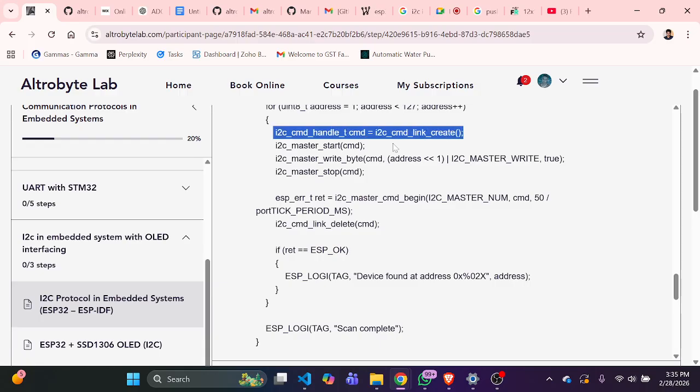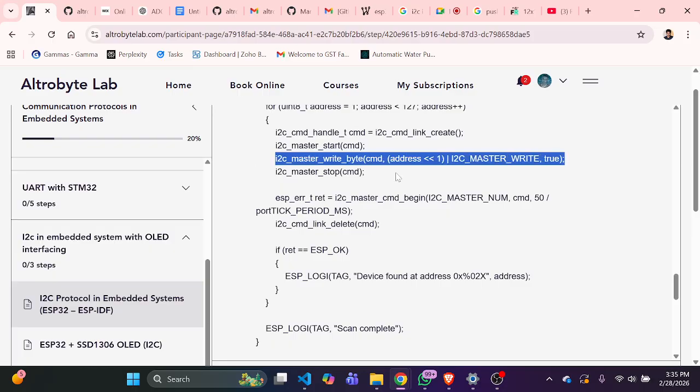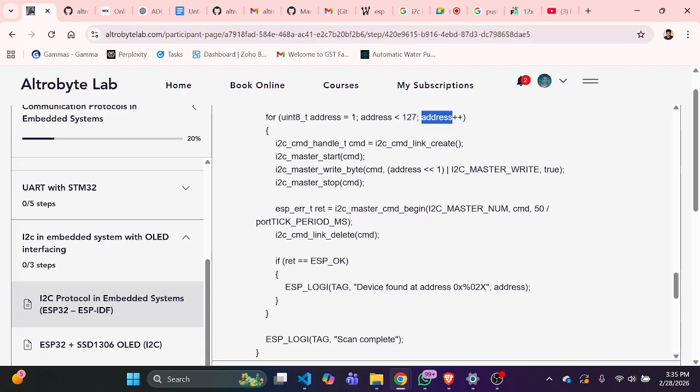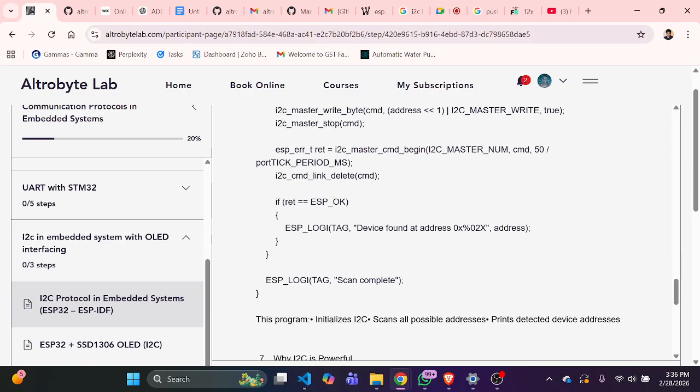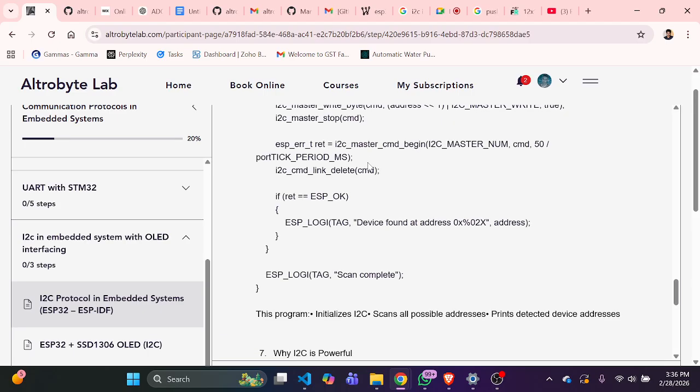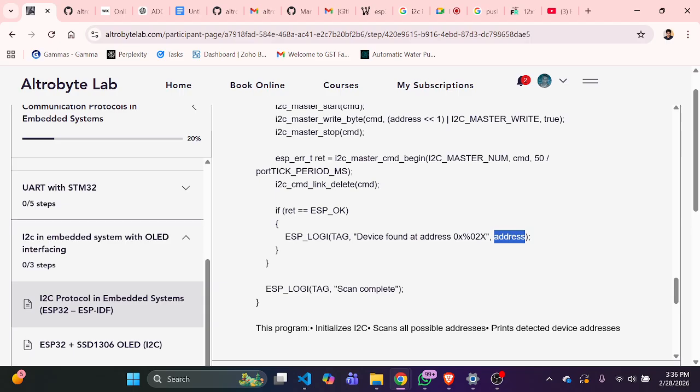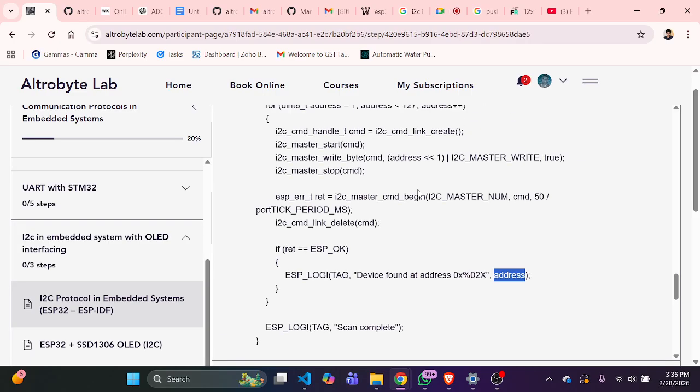After calling these predefined functions, here we are writing the bytes. That means here we are writing the address variable, and after that a stop command. Now we will read the upcoming address, and we will store that into the master address variable here. If the device is communicating, if it responds, then it will send us an address. What is the address of that device?